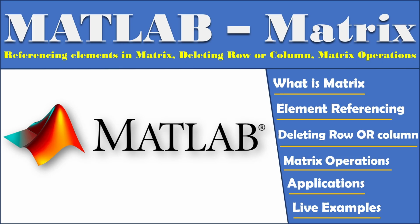We will begin with the theory of what a matrix is in MATLAB, then referencing elements in a matrix, how to delete either a row or a column in a matrix, different matrix operations, applications of matrix, and at the end, as usual, for your better understanding, I'm going to keep this session mixed with the theory part along with live demonstrations of MATLAB scripting examples. So let's start.